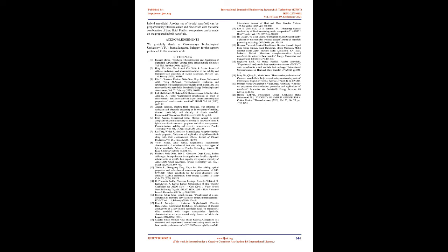19. Density. It was reported that density of Al2O3 nanofluid at 0.5 volume percent of nanoparticles increased with increasing ultrasonication duration. This is because at a lower ultrasonication period, nanoparticles are not well dispersed. 4. Ternary hybrid nanofluid shows increased density with increase in volume fraction of nanofluid for Al2O3-TiO2-CuO/water base. 12. It was reported that with increase in particle concentration, density of graphene nanoplatelet silver hybrid nanofluid also increases at constant temperature, while density decreases with increase in temperature at constant particle concentration.